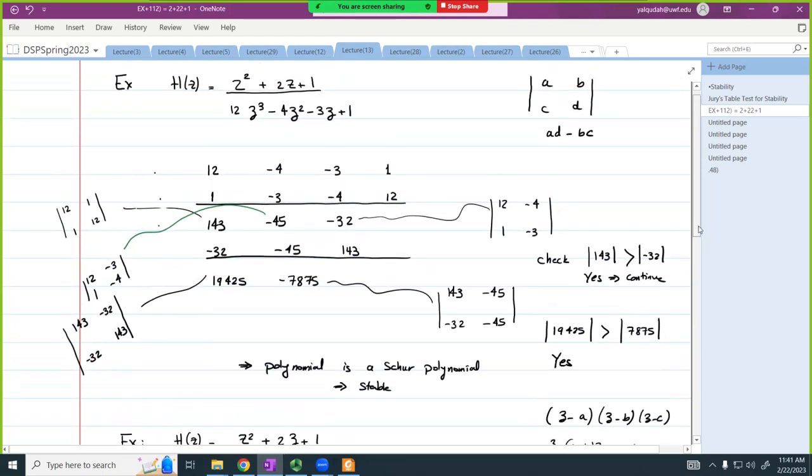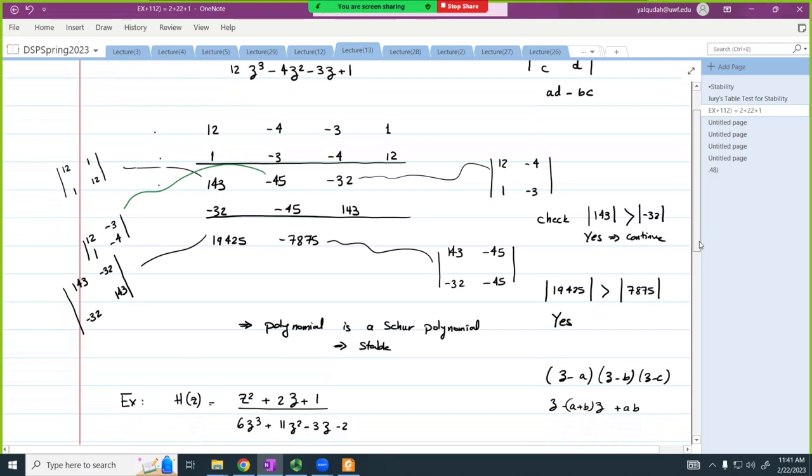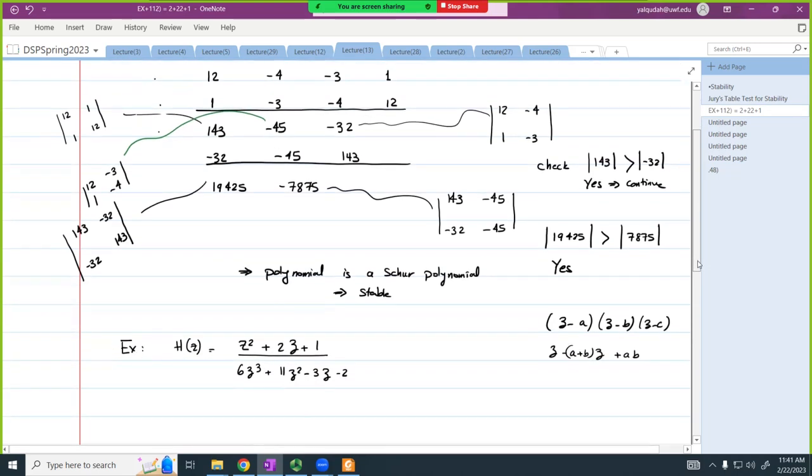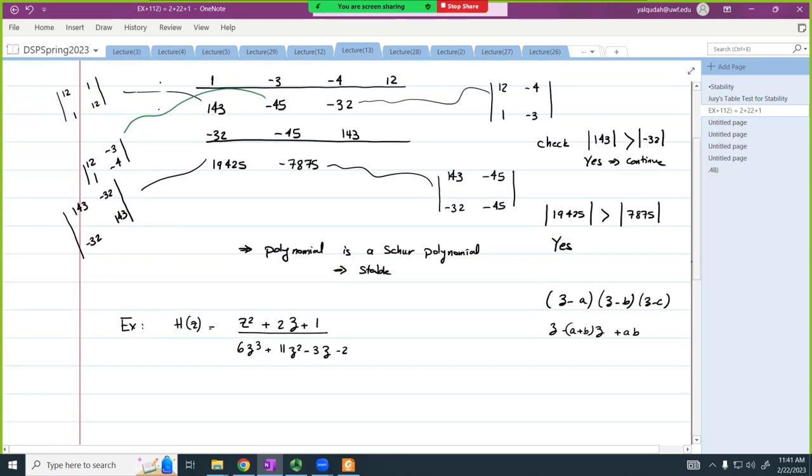Whenever we're doing the Z transform, does the order of the denominator have to be equal to or greater than the order of the numerator? That doesn't matter. The order does not matter because we're only operating on the roots of the denominator. Does that make sense? However, what we have to make sure is there are no poles that will cancel with a zero. So the assumption is there's no cancellation. Otherwise, you could have a pole that could cancel with a zero.